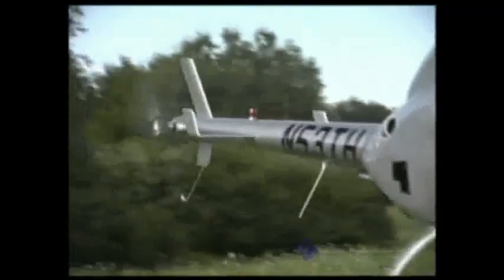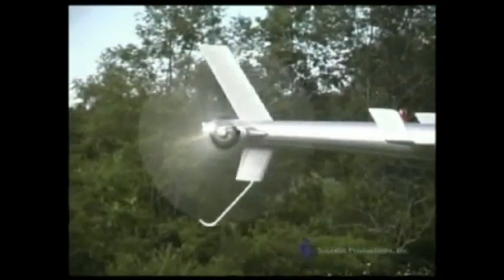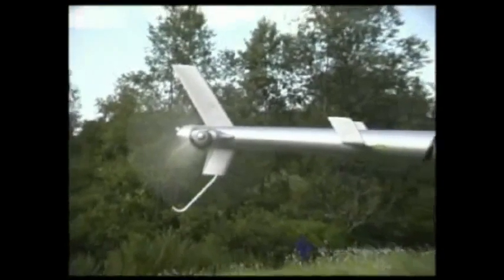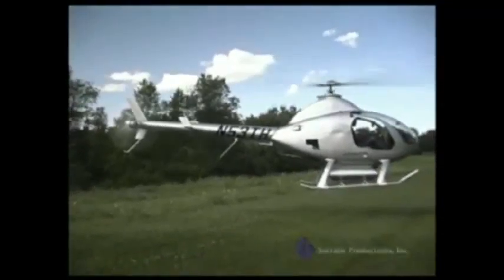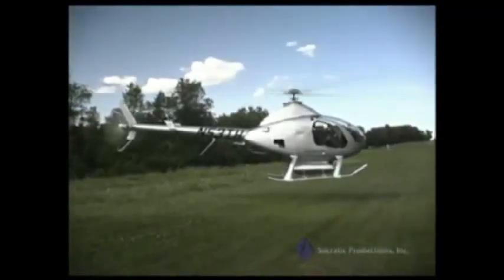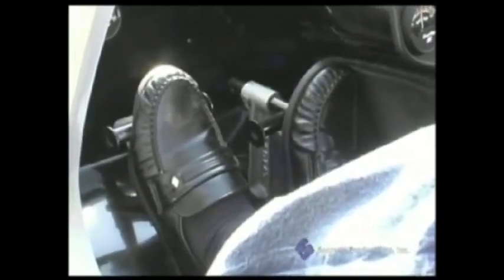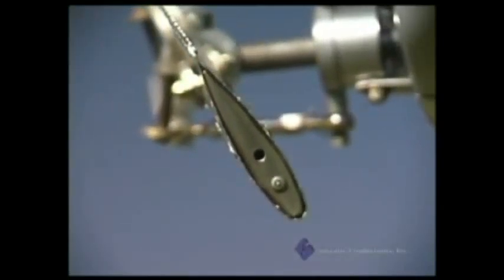In most conventional helicopters, a tail rotor is used to compensate for the torque applied to the main rotor. The tail rotor is installed on a long lever, the tail section, and provides sideward thrust, which resists the turning of the helicopter. To control the tail rotor, we use the anti-torque pedals. These pedals change the amount of thrust generated by the tail rotor by increasing or decreasing the pitch, causing the tail of the helicopter to rotate right or left.